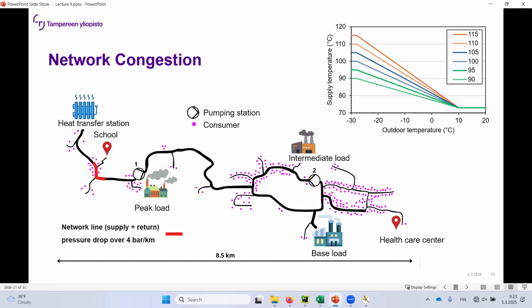Yeah, sure, you're going to have less heat losses, but you are going to have more pumping constraints, or pumping losses. So the pumps are going to have to deliver more water for the same power. And the same power with more water means that there's going to be more flow rate, more mass flow. So you can find these bottlenecks in these networks, where there's going to be too much pressure loss.